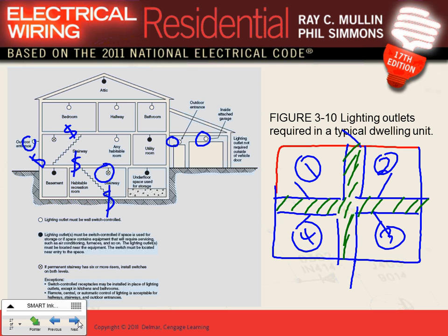So all the lights they're going to be installing in these areas and the receptacles have to be two things: powered and controlled from a public place, and powered from a public panel.